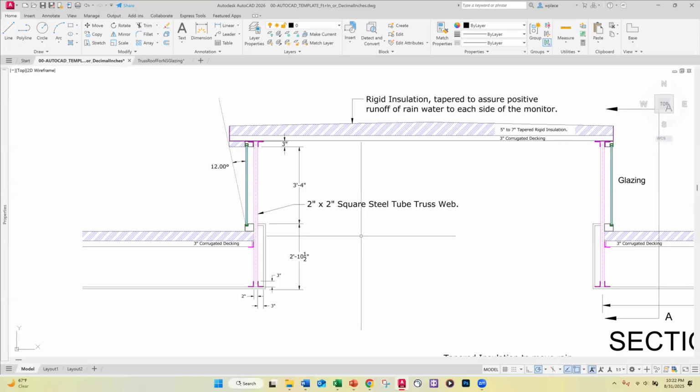and so to give you really simple joints that you can rely on, we're going to make the web members the same width so that the interface of these cord members can be welded to the interface of these web members, and by inner, I mean towards the interior of the building.